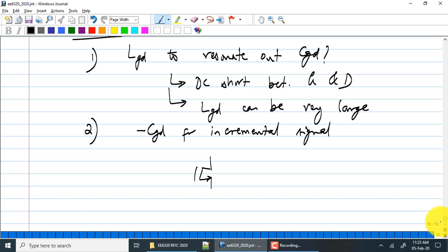How many of you did analog systems 2 semesters ago? You remember the gyrator, which was a generalized impedance converter? You can use that to generate an incremental negative capacitance. Okay, what else? So maybe gyrator or gyrator based circuits, but let me offer you an alternative. You can use Miller effect to create negative capacitances. Okay.